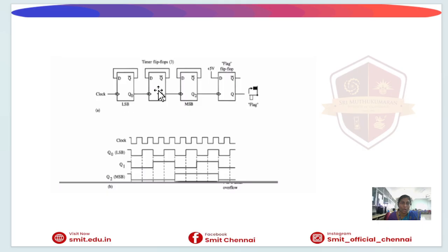The timer counts automatically, incrementing every machine cycle. Then overflow occurs: when the maximum count is reached, the timer rolls over to 0000H and sets the TF flag. Next, stop the timer by clearing the TR bit. This sequence is repeated whenever a new delay is needed.